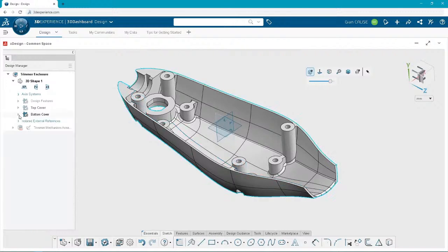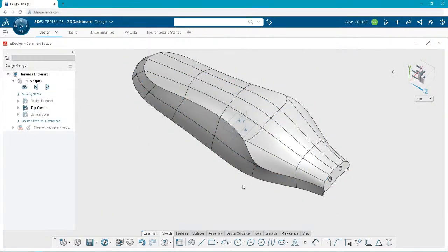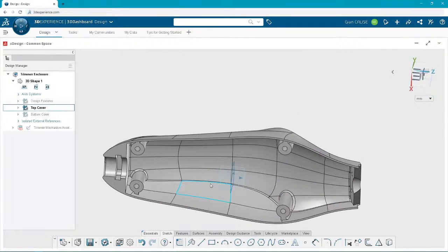All right, so fast forwarding a bit, I'm going to say we've already done our top cover. You just saw how I did the bottom. The top is really no different. So we're going to say, all right, we got our top cover, we got our bottom cover, but now we have 3 OGSs. We have 3 of those ordered geometric sets again in our one component, but I need separate components.